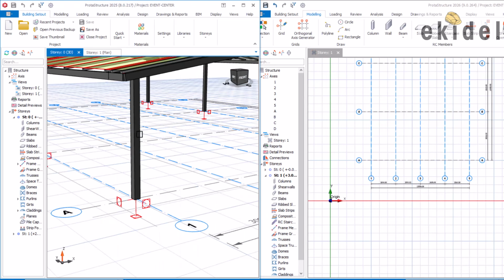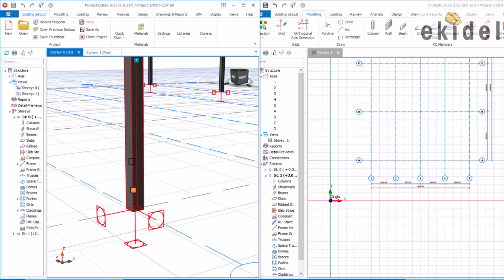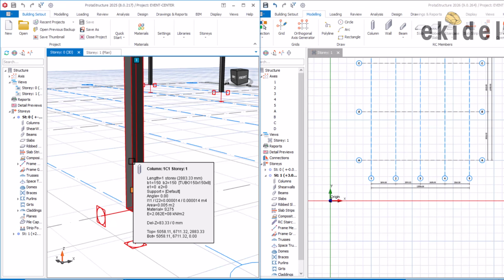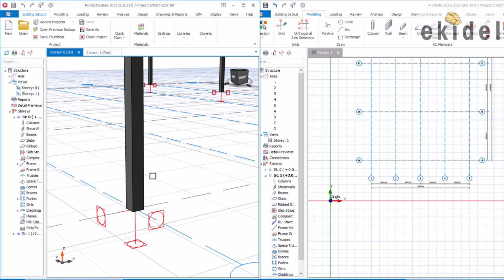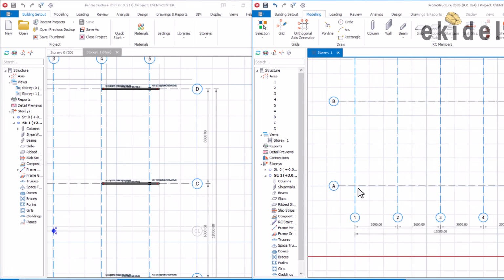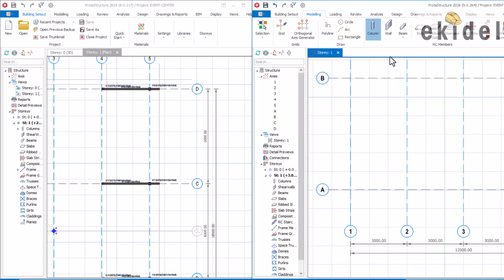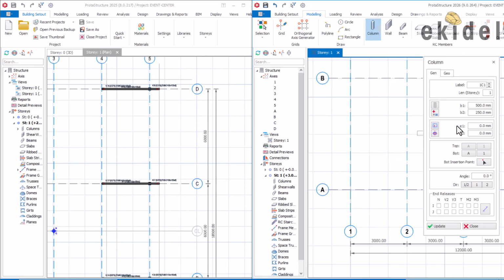And what is the size of this T stanchion? Because this has already been designed. This is a 150 by 150 hollow section. So we come here, hollow section, then take our pedestal, put on 0. Then come here and type in our values. Since it's 150, we are going to use a pedestal of 250 by 250. Okay, that is fine.